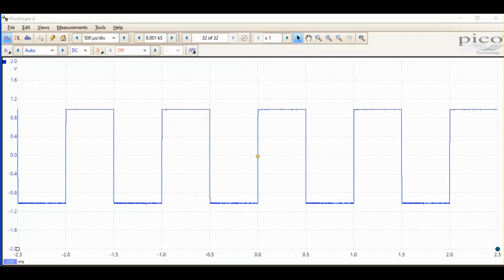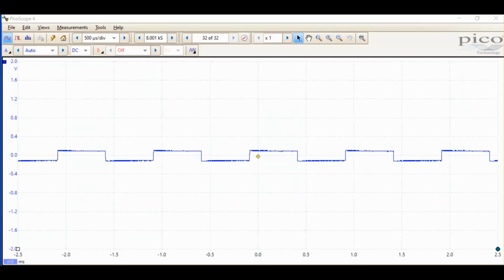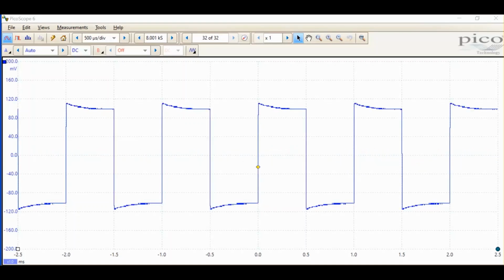At the moment, the probe is set to ×1, so the signal passes straight through the probe without any attenuation. When we switch to ×10, we see the signal gets attenuated and then the vertical scale auto ranges, and we are now presented with a distorted signal that is typical of an uncompensated probe. What we're seeing here is a probe that's not maintaining a 10:1 ratio evenly throughout the frequency range. All that's required is to adjust the variable capacitor in the probe compensation box using the adjustment tool provided until you have a relatively flat top.